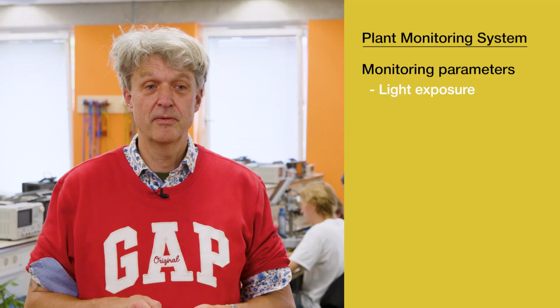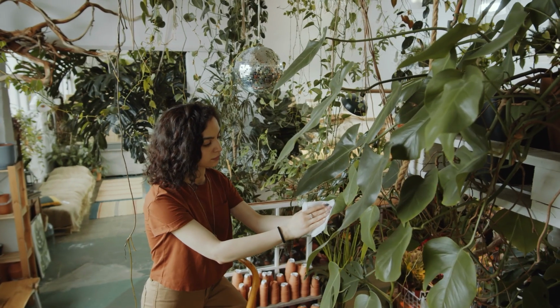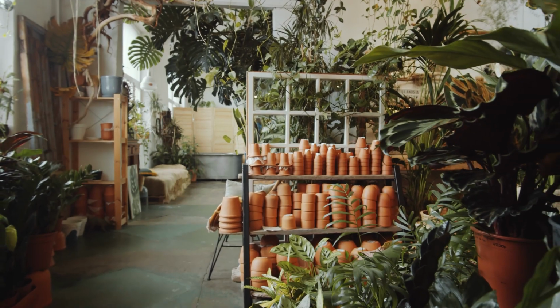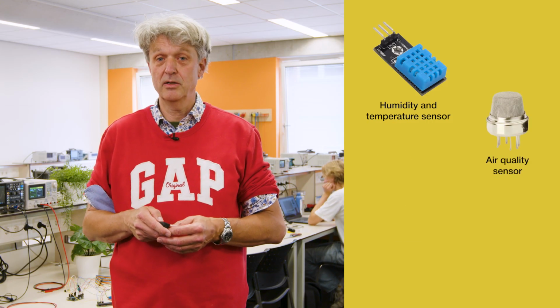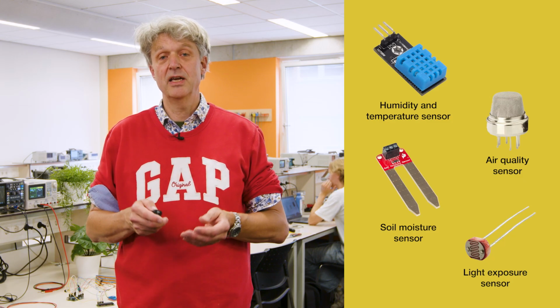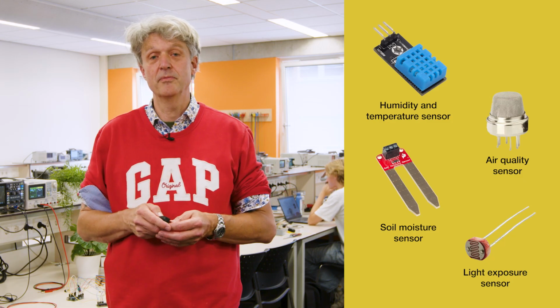So what do you need to control when you want to monitor a plant, and what do you want to do when you want to take care of the plant? Light exposure is an important factor, air temperature, soil moisture, humidity and air quality would be measurable parameters. But to control and take care of the plant, you would maybe water the plant automatically and have nutrients delivered automatically. For this purpose we have a number of sensors in place. You can find a humidity and temperature sensor over here, an air quality monitor sensor, a soil moisture sensor and a light exposure sensor. These sensors gather data which needs to be sent to a computer system.